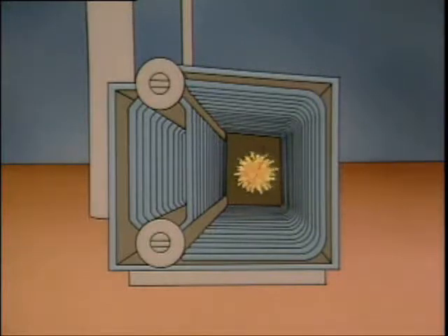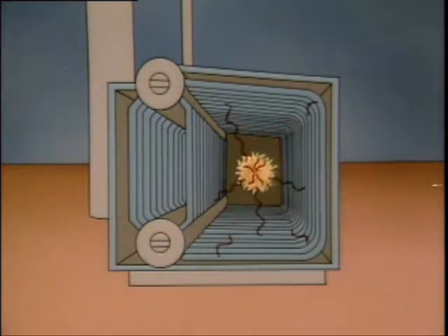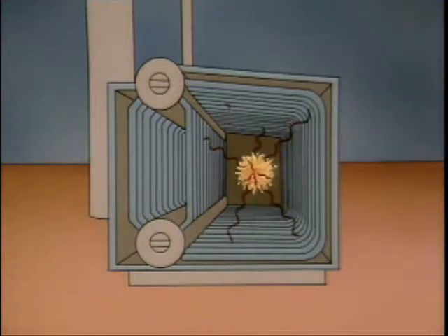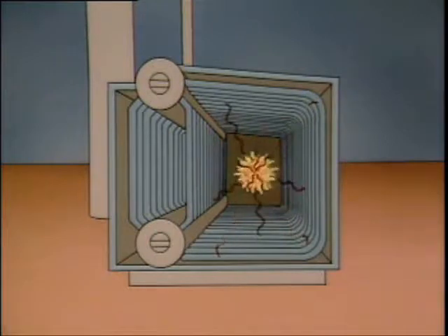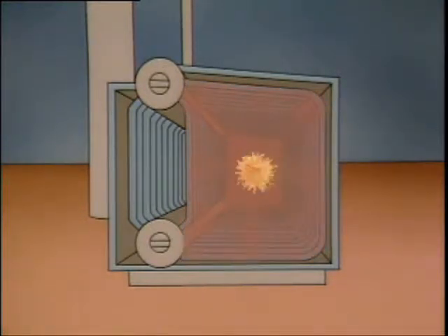When fuel burns in a boiler, radiant energy in the form of electromagnetic waves is produced. These waves travel through the combustion area. The waves in a direct line of sight with the tubes make contact with the outer tube surfaces, and the tubes absorb heat. This is radiant heat transfer. The burning fuel also produces combustion gases. As these hot gases pass through the boiler, they transfer heat to the tubes as well. This is convection heat transfer.